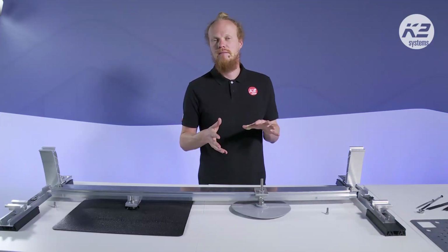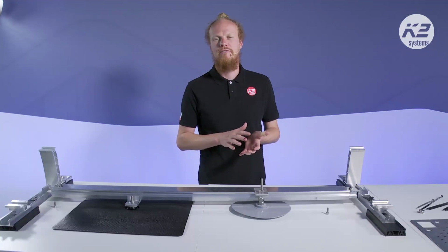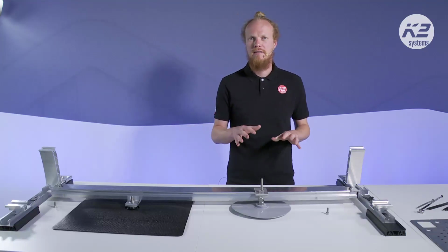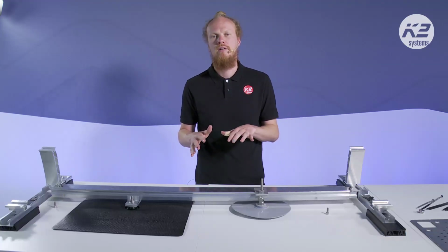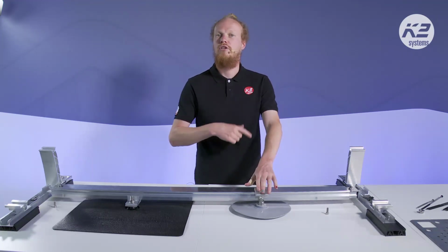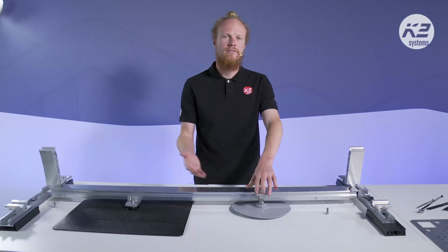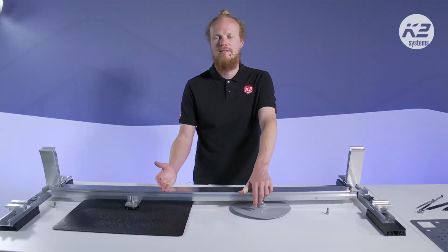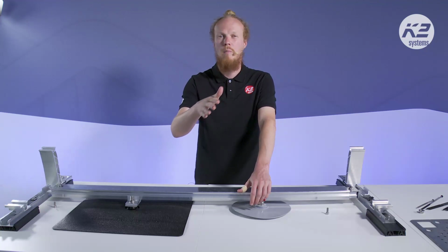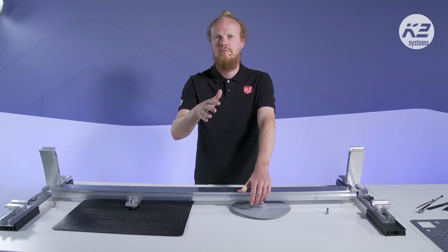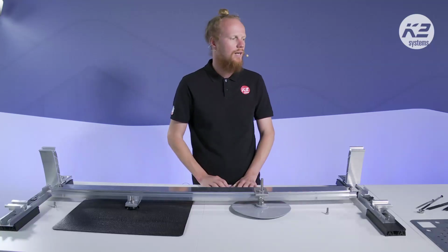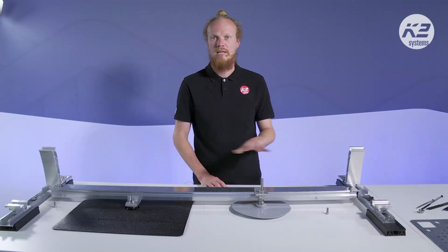So we have a building that has a friction coefficient, and from that we determine what is needed to secure it. So whether that be ballast or anchors, there is a force sliding down the roof. Determining that force and the forces required on the fixations will determine the number of anchors. So yes, we might have a fixed system, but how do we know it's fixed? We can say if it has 4 anchors, it might slide down, but if it has 8 anchors, it might not slide down. This is a point that comes after the question of will it slide down in the first place. So the friction coefficient is something that you need to put in regardless of the roof.